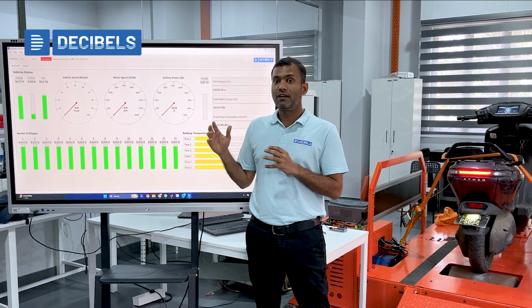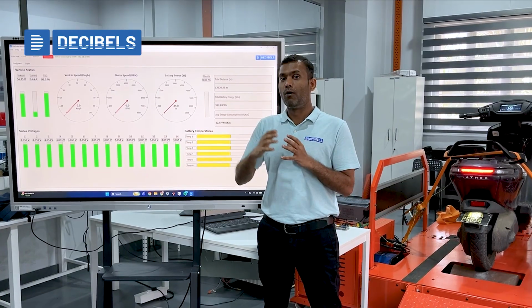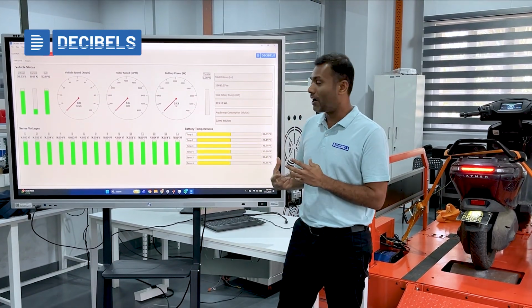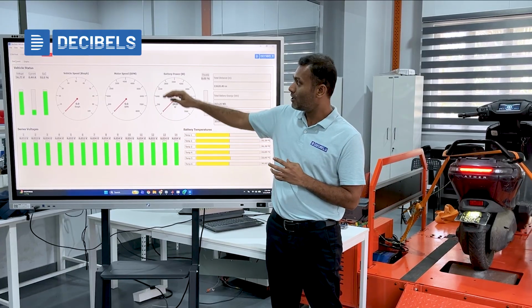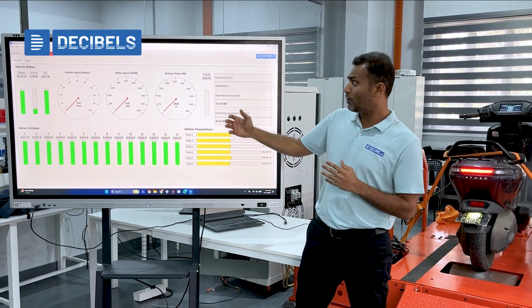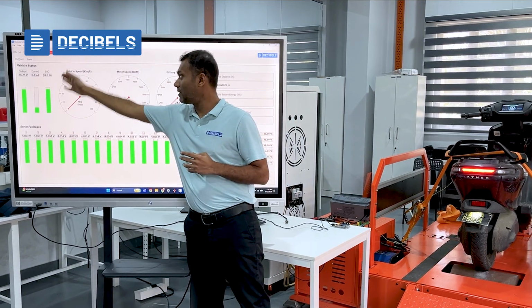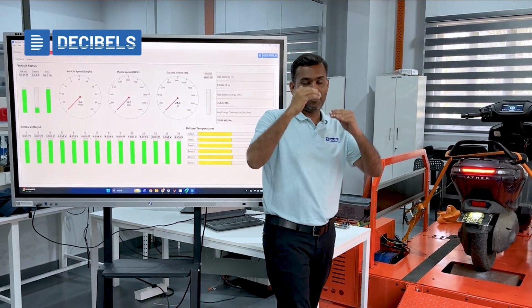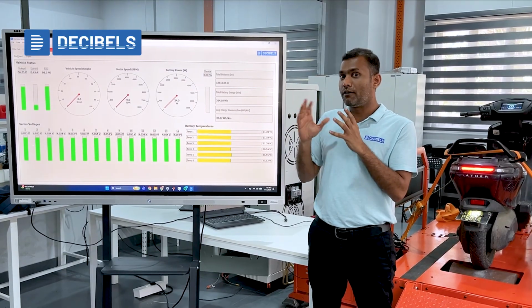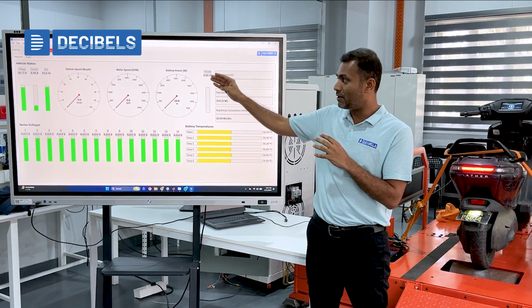And if you're driving in a variety of different modes or conditions of operation, you can check how the terminal voltage changes with respect to the battery current. Also, because we have the SOC function given here, we can correlate with respect to the SOC how the terminal voltage of the battery pack changes with respect to the battery current.